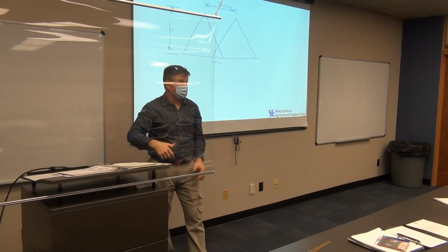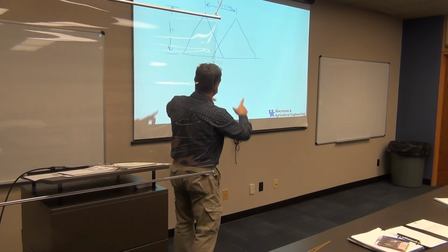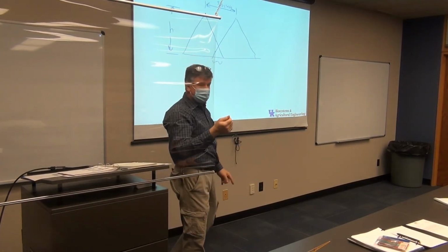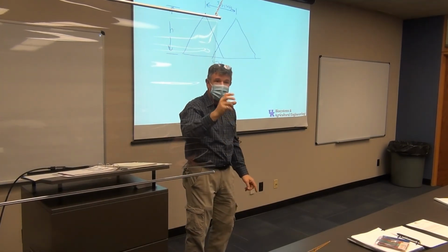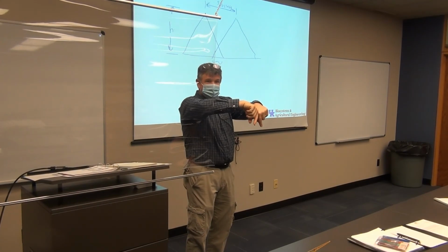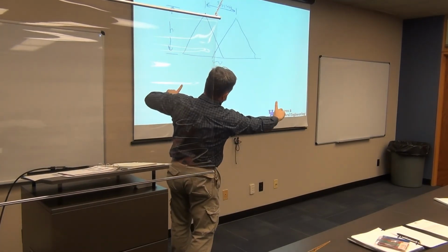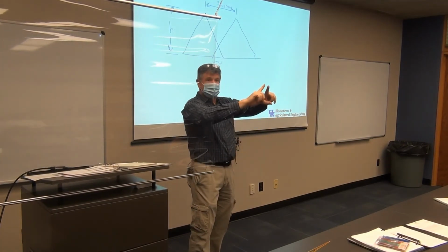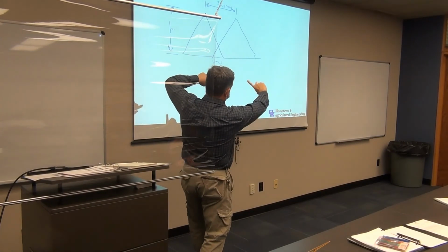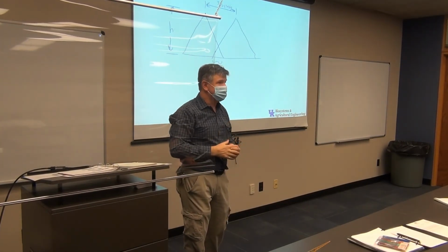How much does that need to overlap? Again, different nozzles are designed with different patterns. Different nozzles are designed with a different angle up on the top. I'll show you on the nozzles tomorrow or Wednesday that typically they're either 80 or 110, and there's numbers on there that show us that. So that angle, left to right, coming down from that nozzle is usually 80 degrees or 110 degrees. So they're either relatively narrow or relatively wide. That's what you typically see on those nozzles.